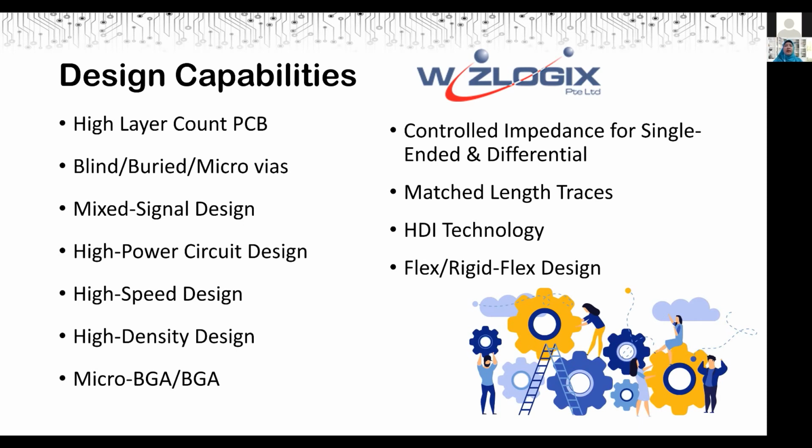On top of that, we are also capable in designing micro BGA, BGA, ASIC, ICs designs. And if you require layout design for controlled impedance, for single ended and differential pairs, we are also capable with matched length traces. And we do have experience in designing flex and rigid flex design. So the HDI technology is also referring to the blind, buried, and micro vias.